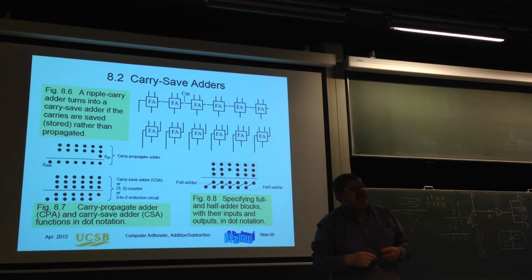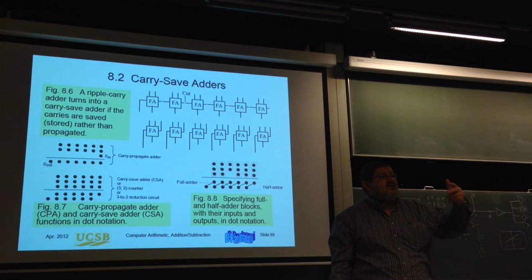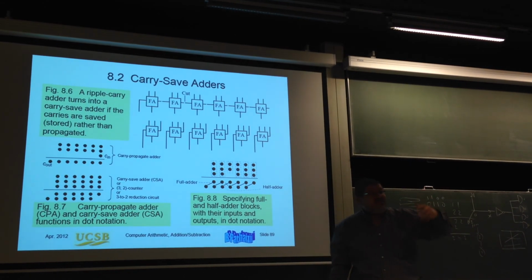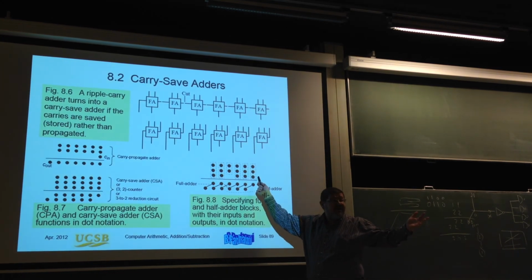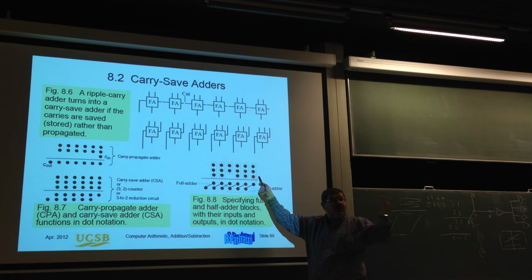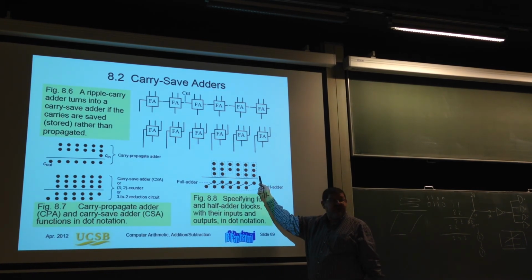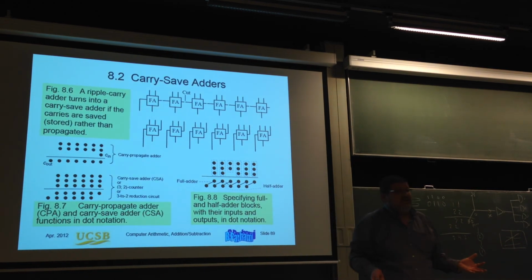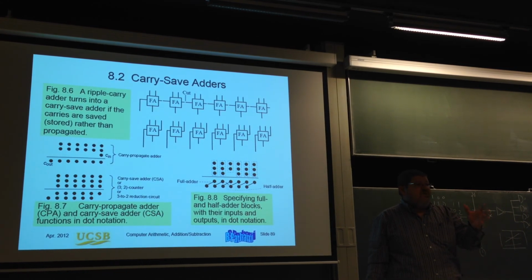And now you can already see what the idea will be to do multi-operand addition. I take those numbers in pairs, and I can do that kind of reduction. I can do that serially or in parallel. If I do it serially, my cycle time will not depend any longer on linear or logarithm of n, it will just be a full adder delay. If I do it in parallel, you will see I can get even better. And that's the beauty of carry save addition, which is postponing the propagation until it's really, really necessary. And that will be necessary when I add the last 2 numbers. The previous value, which I accumulated, with the current value, I obtain now 2 numbers, which don't make sense because I want to store them in a register and decide something based on that result. And then I would have to apply a carry propagate. We'll discuss about that after the break.